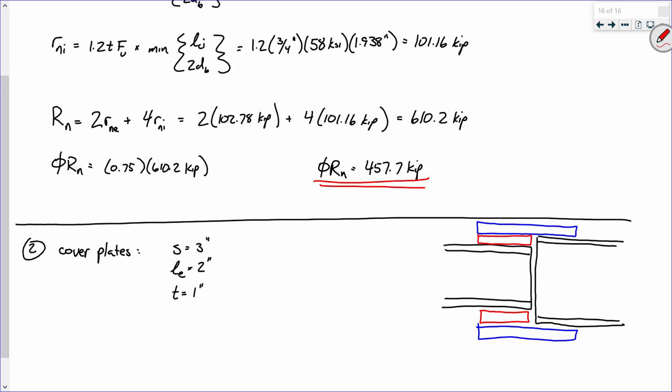Those cover plates are the ones really taking on the large majority of the work being done. Now, let me also say this, you can have multiple filler plates. If you're trying to do 3/16 of an inch, you might put something like 1/4 of an inch or 1/8 of an inch and then another 1/16. So you might have multiple filler plates in there, but mostly friction is what they're going to be seeing, and that's about it. This is good stuff. Anybody have any other questions? This is really good. All right.